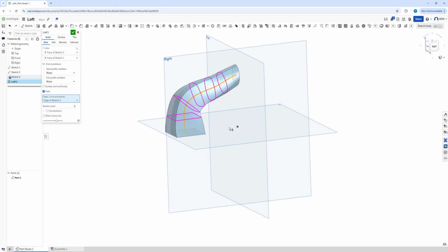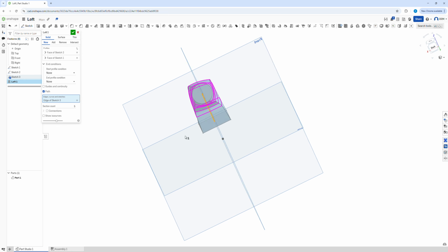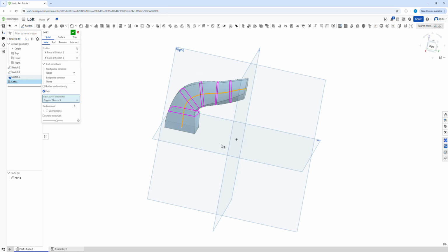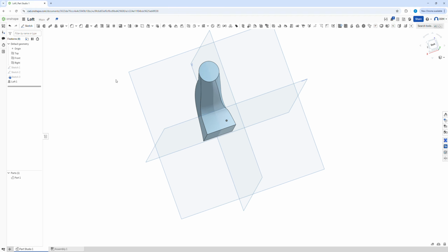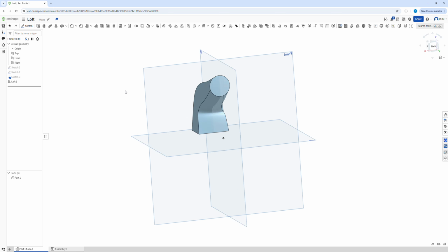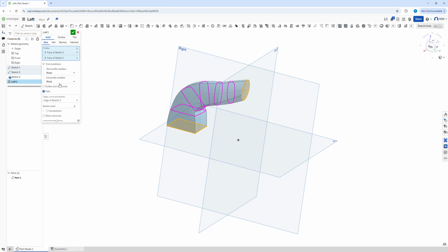And as you can see, it has now very cleverly decided how it is going to make this path work. It's going to follow this path along, with these different profiles. So I can green tick that, and I now have my Loft tool following a certain guideline. If I go back into it, maybe you also want to try and add your normal to.